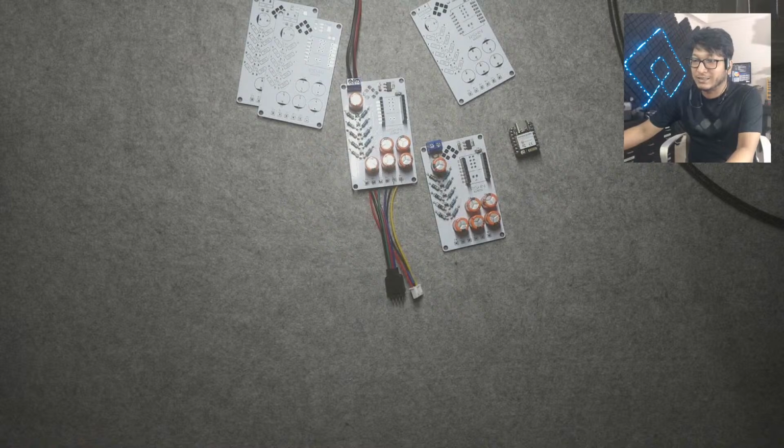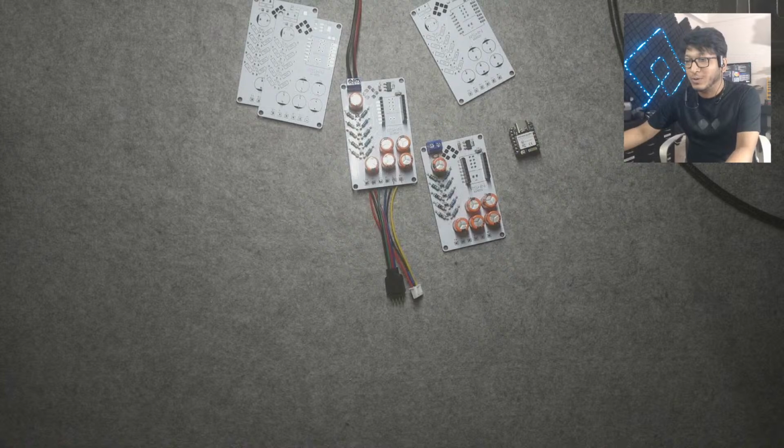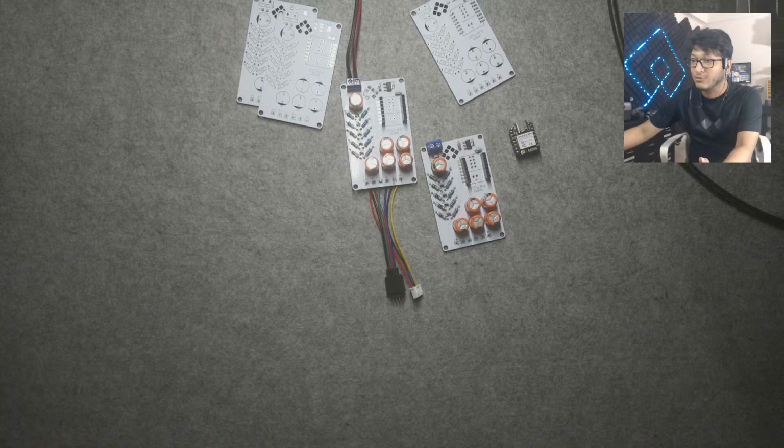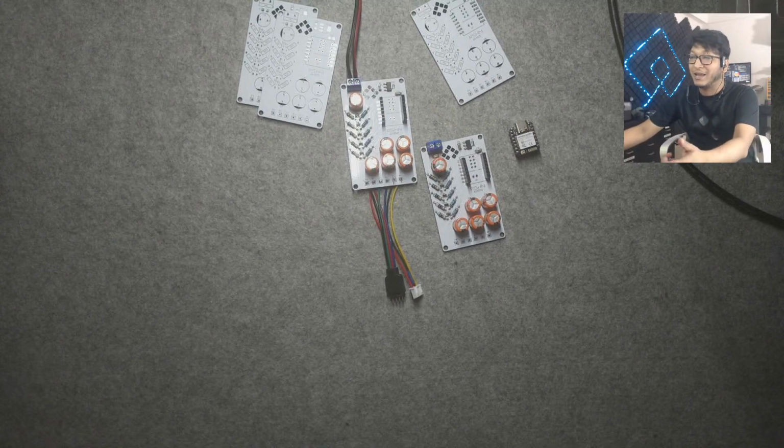I could trace the lines back and forth. With a 2-layer board, if something is coming along this line, there is no other port on this side that I can use for the 5th input. So the 5th input has to come from the other side, which means this entire line is blocked. If I have to take anything from this side to that side, I have to go down and take it from the other side, and then from the other side I cannot take anything from this side to that side. So it's a mess.